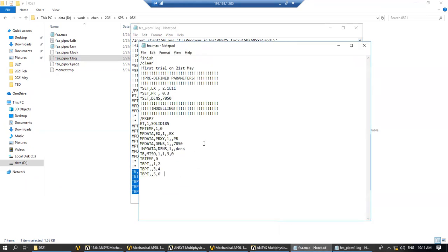So it could be like this, and of course these values have to be changed. The strain will be 0.000 something, and this stress could be like 400. Depends on the yield stress of the material. Normally the first value is the yield stress. So let's say 300, if we want to use 300 MPa.